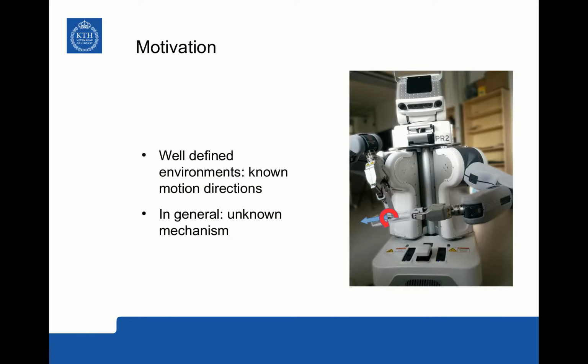We focus on manipulation under geometric uncertainties. When all the relevant geometrical information of a given manipulation problem is known, the task is relatively easy to accomplish with traditional methods. In unstructured environments, however, an identification method is required in order to determine the properties of a mechanism. These are the direction of the available degrees of freedom and location of the mechanism's joint.